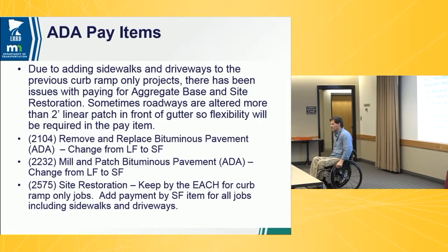At our curb ramps, for example, we were paying for the concrete walk, with the gravel being incidental, but we're paying for the gravel underneath the sidewalks. It's hard for construction to tell what's incidental and what's paid for. So we backed out the incidental gravel underneath the curb ramp. Now we're paying for it as compacted volume, 3 inches underneath the curb ramp, the walk, and the 6 or 8 inch driveway. We recommend that not be a planned quantity, so construction can use it as they see fit.